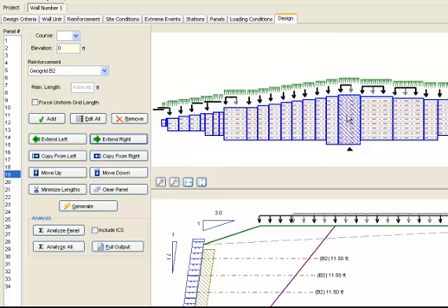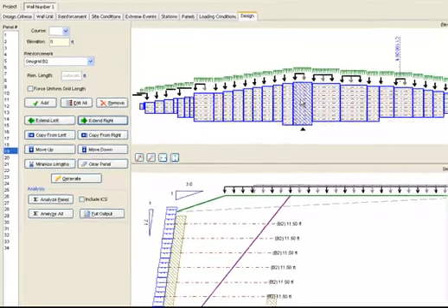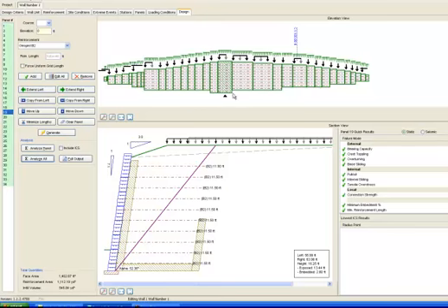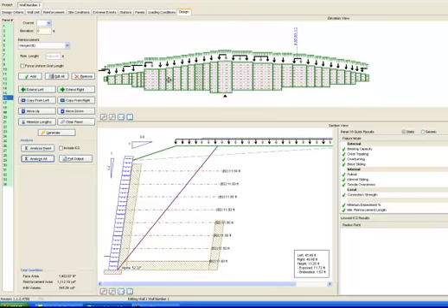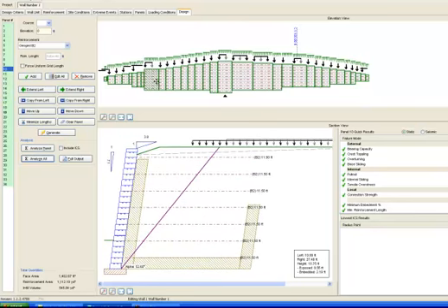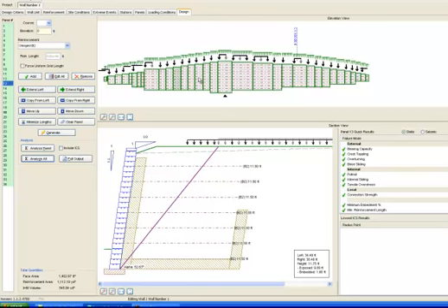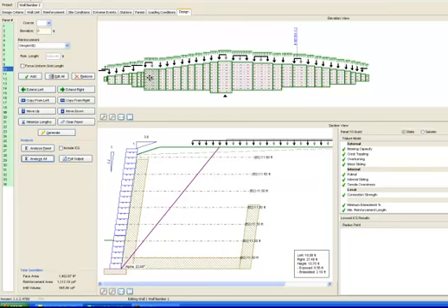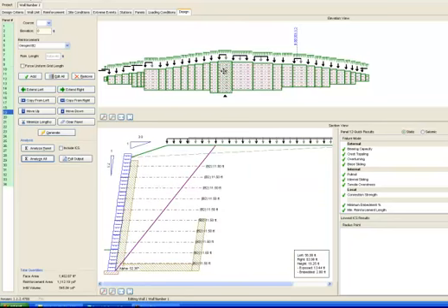Our next step would be to get an initial idea of where our design stands for the wall as a whole. With the Include ICS button off, hit the Analyze All button. We can see that all of the panels are now green, signaling that all of the design criteria have been met for every panel, which is not surprising since we extended the Geogrid layout from the highest panel to lower ones. If a panel did not pass the minimum criteria, it would be shown in red. However, this design would likely be over-conservative as it stands, since many of the lower panels will have Geogrid lengths that are applicable to much higher sections.